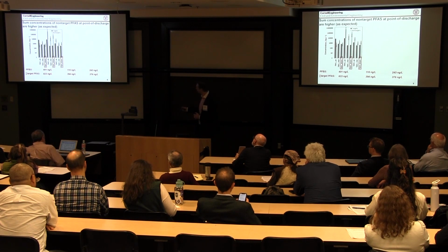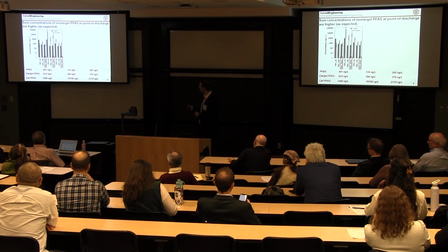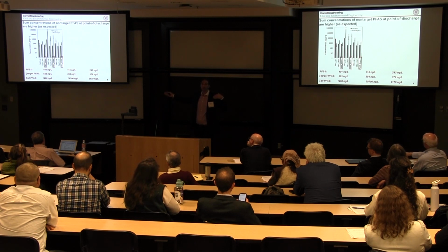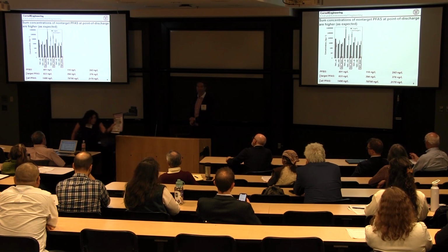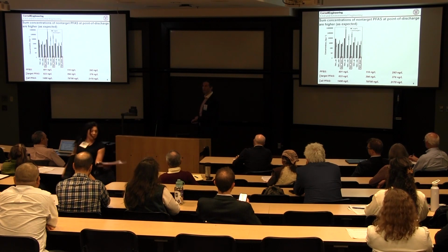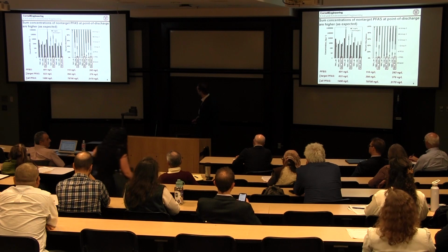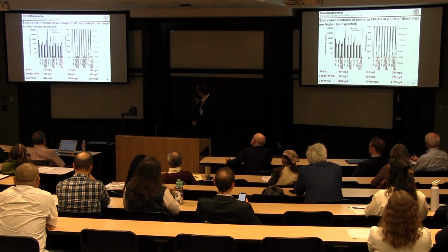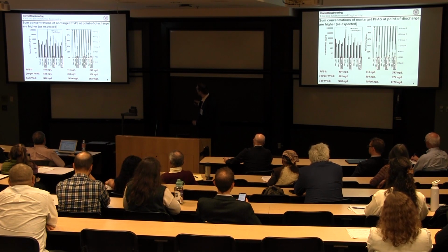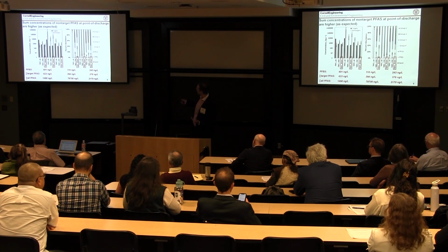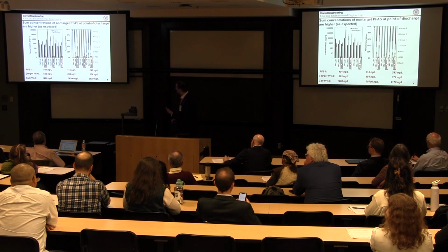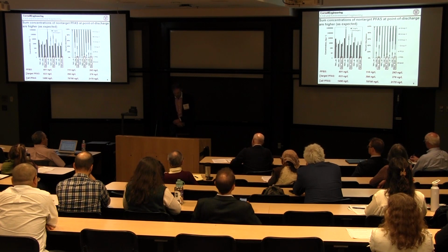This was the data that I showed in the first half. If we now include all of the PFAS, including the non-target PFAS, you can see that increases the estimated concentration from anywhere from 2-fold to 200-fold. So including these non-target PFAS can be really important when estimating the total fluorine burden in wastewater emissions from these types of facilities. And this last figure just shows it as percent abundance, and the key point that I want to make here, these being the non-target PFAS, these being the target PFAS, also on a fractional basis, the majority of the PFAS found in these wastewater samples are non-target PFAS.